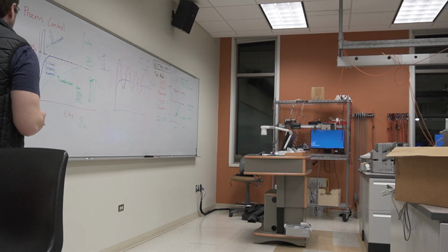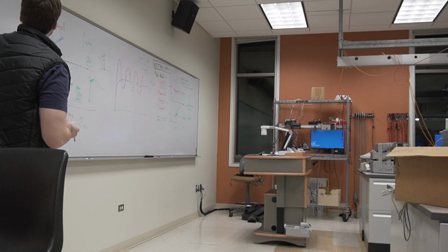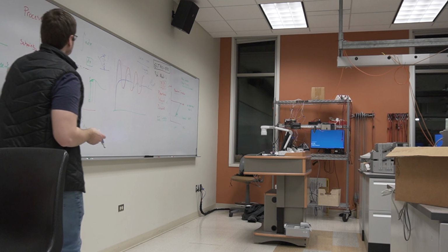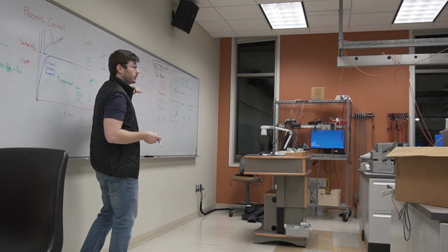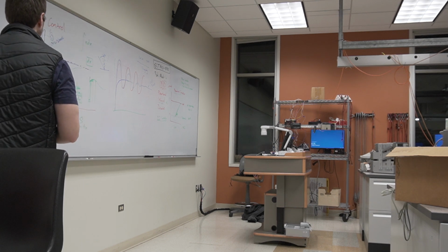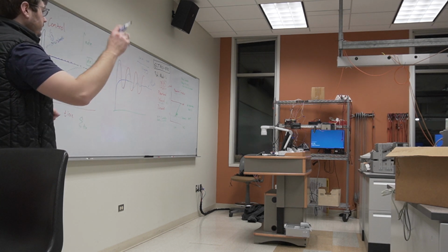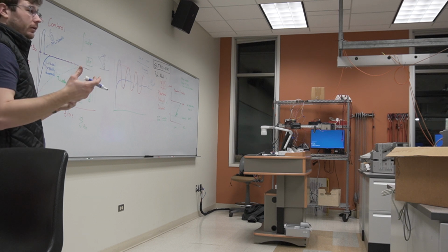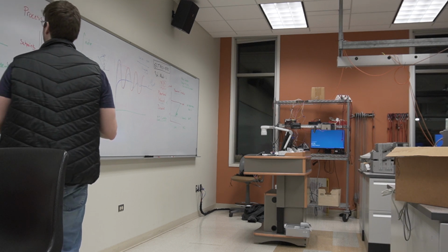There are really advanced ways to figure out what P and what I are in order to get these parameters, but sometimes you really just have to test it. There are algorithmic ways that you can run simulations and have the microcontroller figure out what it's doing and tweak itself.